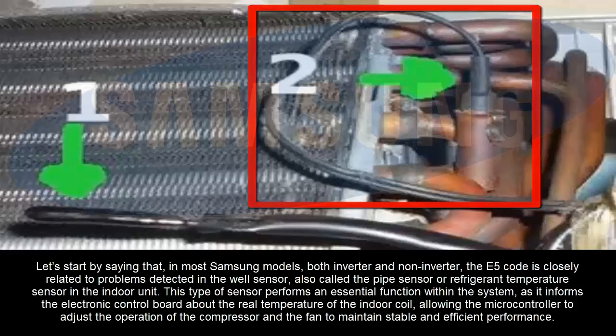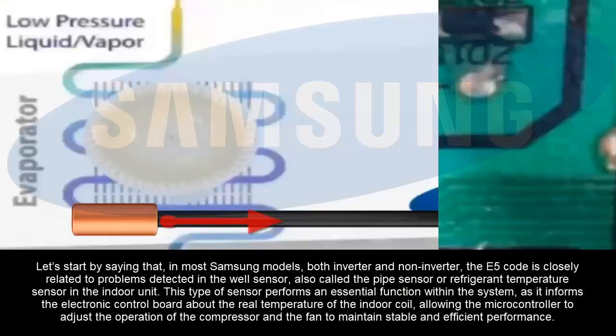is closely related to problems detected in the well sensor, also called the pipe sensor or refrigerant temperature sensor in the indoor unit. This type of sensor performs an essential function within the system, as it informs the electronic control board about the real temperature of the indoor coil, allowing the microcontroller to adjust the operation of the compressor and the fan to maintain stable and efficient performance.